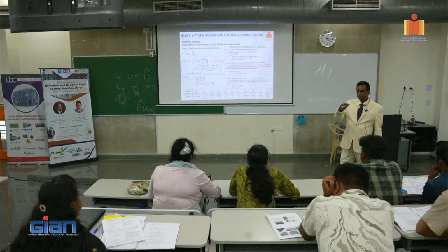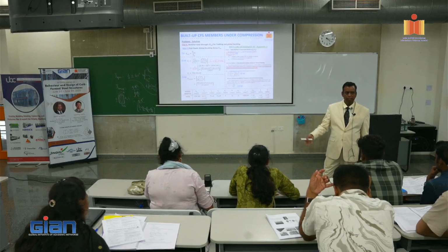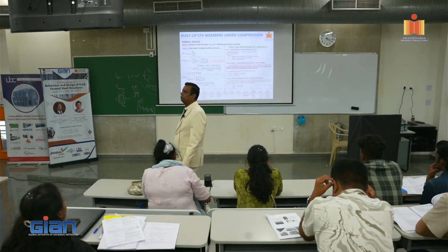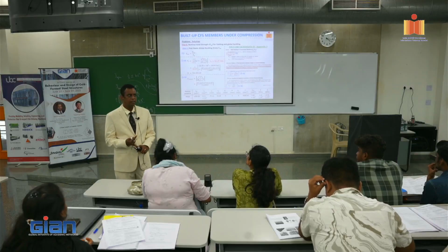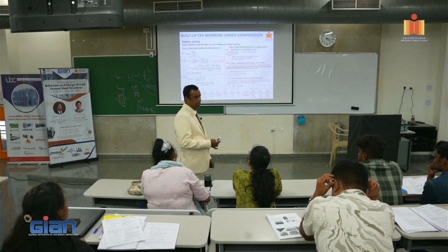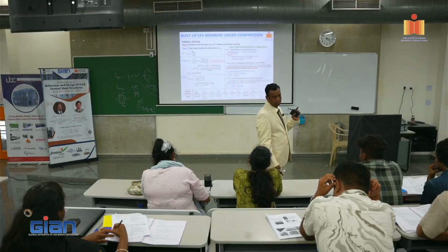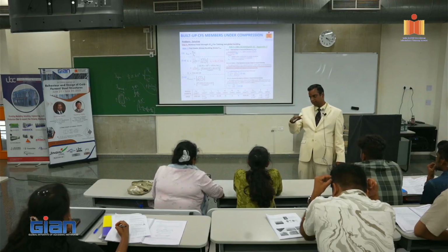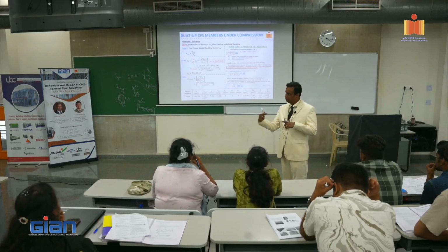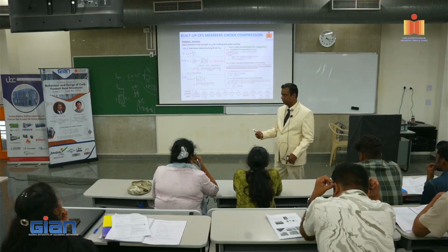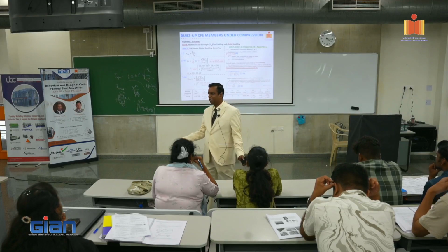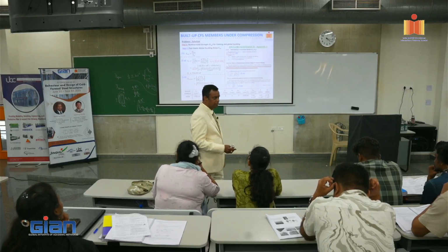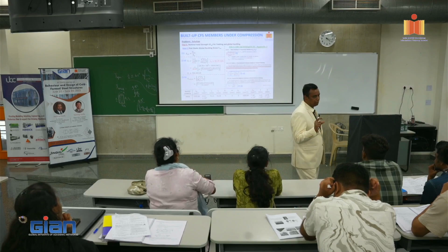So in the major axis it is buckling as a whole, right? In the minor axis it is buckling this way, right? In the major axis, what is the advantage? You have a greater IX, but the disadvantage is the length is more. In the minor axis, the advantage is it has a shorter wavelength, that S curve is coming, because of this nogging or blocking or whatever you are doing. Bridging, blocking, nogging, it's all bracing, right? But the disadvantage is that the moment of inertia Iy is smaller, right?